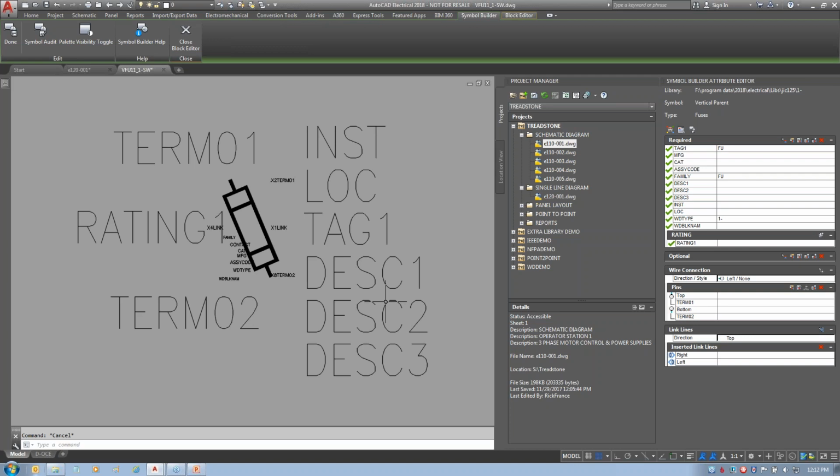This is the one that does all the magic that tells it it's a single line symbol. And as you can see over here, WD type is set to 1-. On a normal schematic symbol, you do not have to have the WD type attribute in there. If it is included, it can be set to blank, or set to no value.